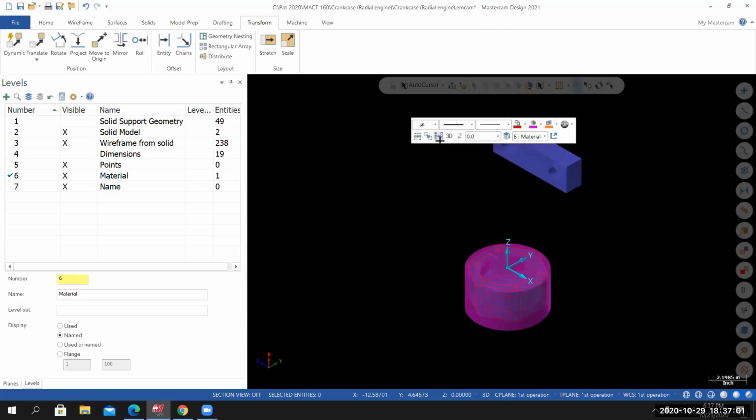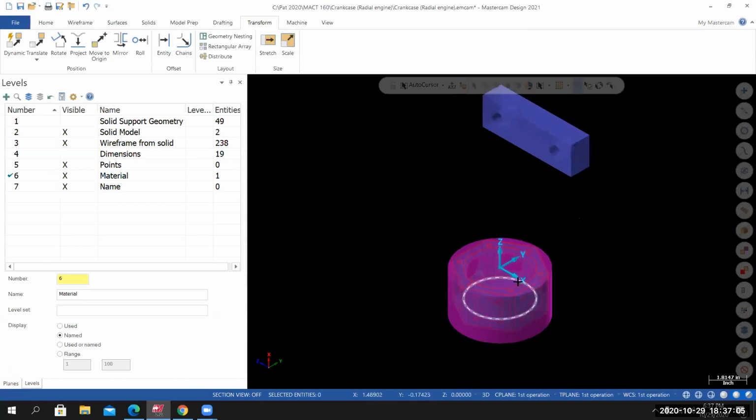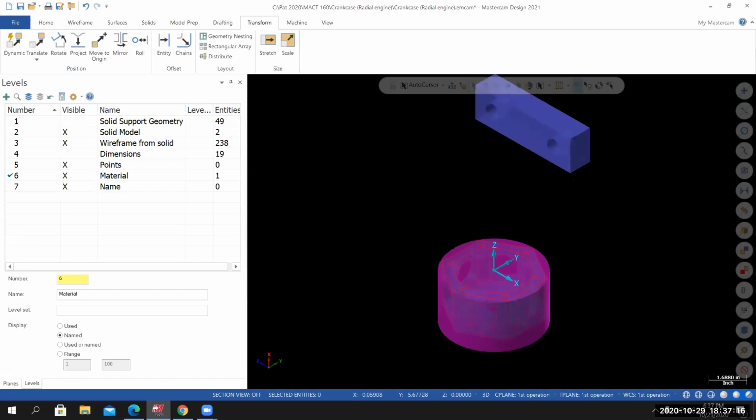How's everyone doing? So this is challenging. So you flipped, how do you flip it? I rotated it so that the counterbores were facing the part. So you visualize these jaws in a vise. Let me pull up a picture real quick.